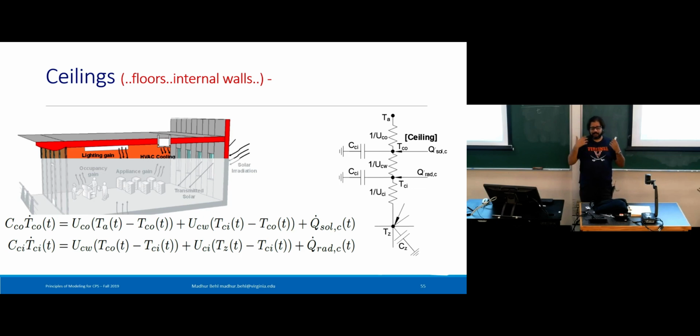So you can, as a designer, as a modeler, as a building automation expert, lump these things together when they make physical sense. So really, you need a separate branch only if the boundary condition is significantly different from other surfaces. That's what it boils down to. So this applies to almost all surfaces. There are some exceptions to this rule.